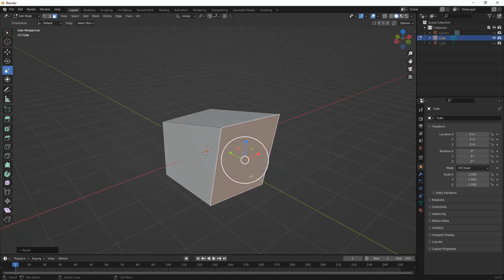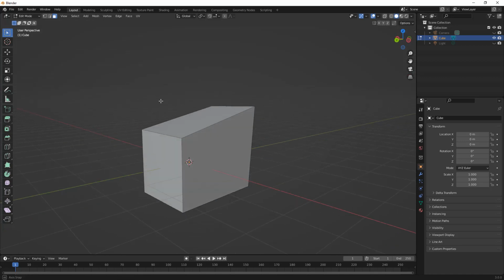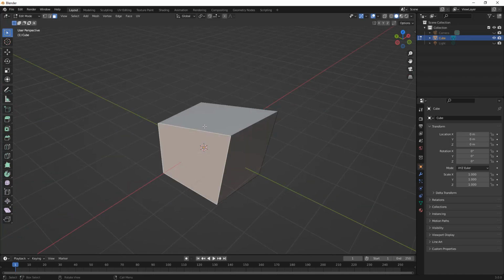And once again, there are plenty of shortcut keys to make this happen. In this case, the scale shortcut key is S on the keyboard. Once we get into learning those shortcuts, we can also identify different ways in which we can scale in just a single direction or scale in plane. But for right now, again, we are going to focus on using these tools. One important thing to note is that even if we deselect our face, our tool is still active. While this can be helpful, it's a good idea to remember to go back to your selection, and that way you make sure that you're not accidentally manipulating your geometry.